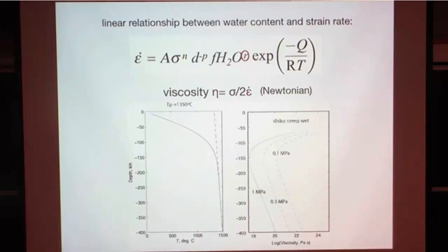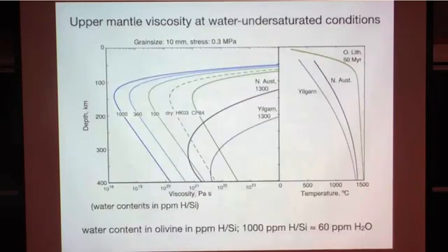It depends on all of these parameters, but for a power law, this is linear, but if you have a power law in here, so this n is greater than 1, in this particular case 3.5, then the viscosity that you calculate depends on the stress that you apply. So that's an important point, but again, jumping forward a little bit here. So why is there a grain size dependence in the last equation?